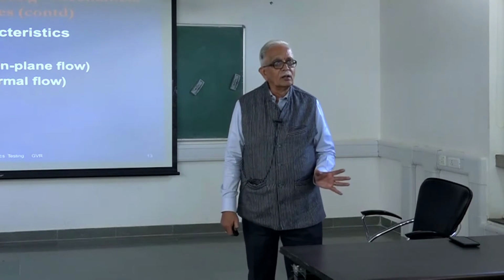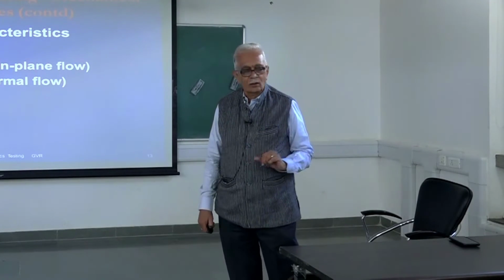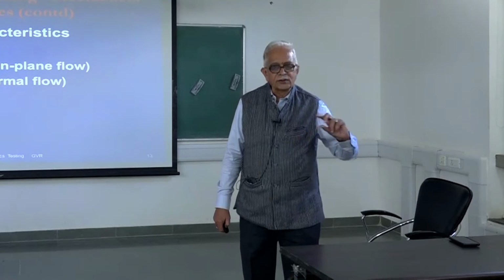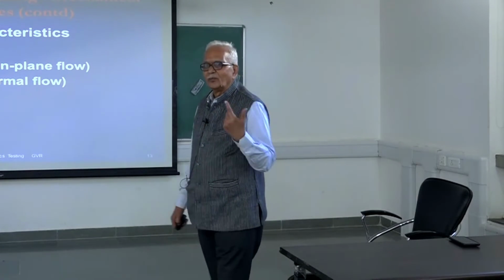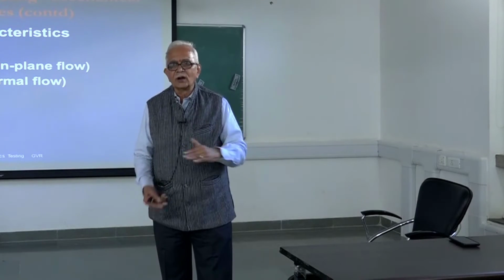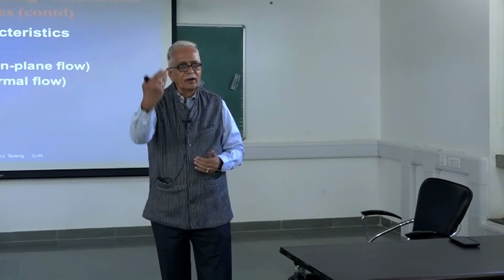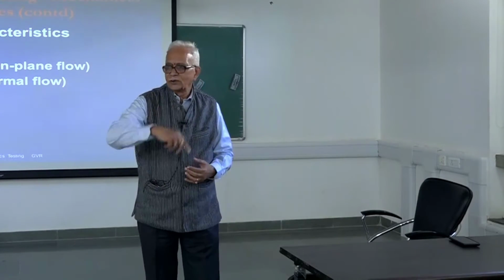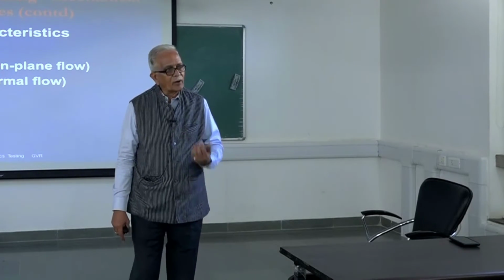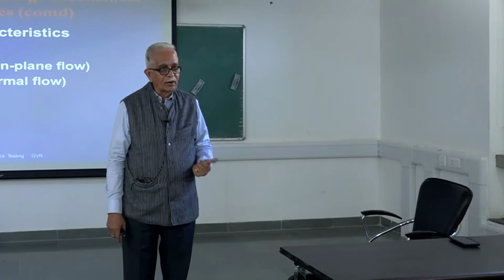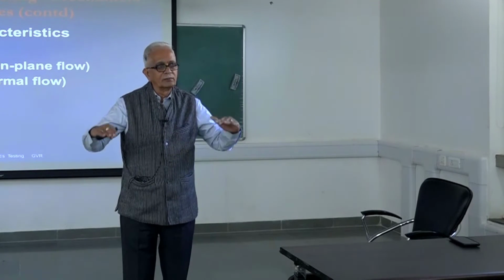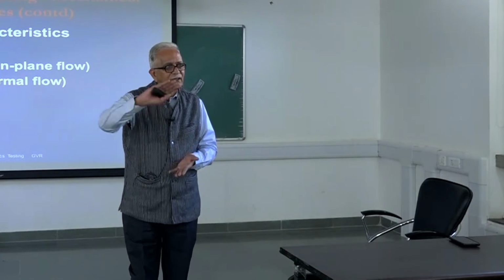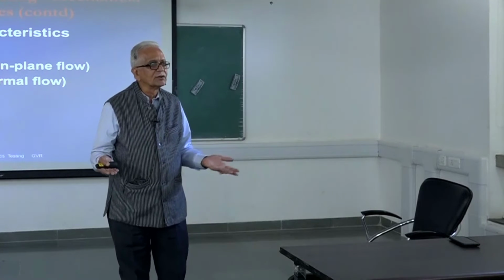One of the hot topics actually is that, I have shown you the drainage composite now, what exact discharge capacity is a point of, I don't know, controversy, a lot of discussion, because each company will provide a kind of composite. Now they may claim that the value is going to be high, but in actual conditions it's going to be a problem. Even a PVD we are talking of, I have shown a PVD which is just in an open system now. We just have a geotextile and we have a central core. But once it is installed in the soft clay, what is going to happen now? Naturally, soil is going to settle through consolidation. So this will not be vertical now, this will be crooked like me. So when it's crimped actually, naturally the discharge capacity is less now.